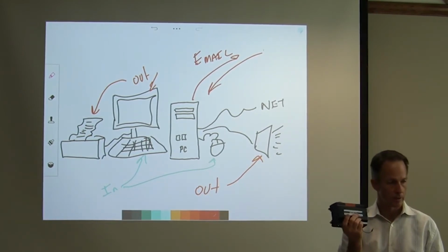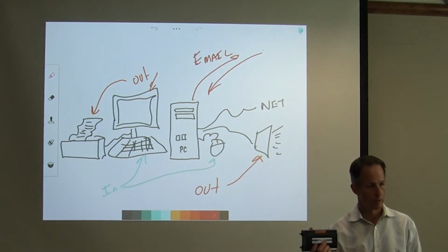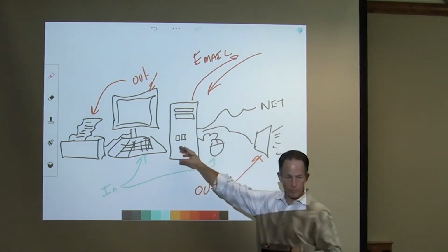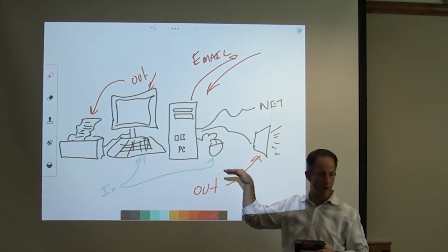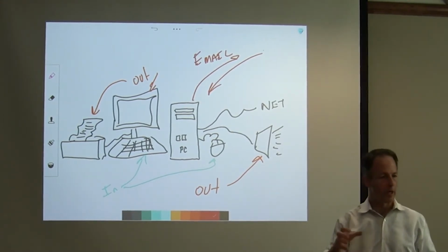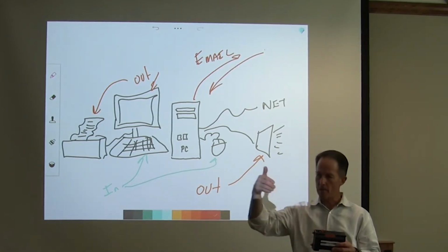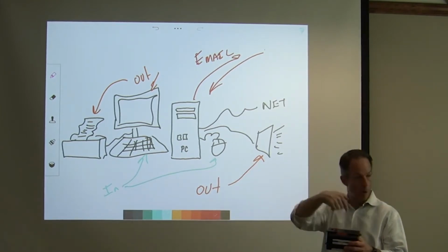You set it up in the supervisor as a network output, and then for each one of the JACEs, you tell the JACE to go look at that network output and tie it to an input. It becomes a point in the supervisor, one of the points that it's monitoring. I could redraw this, but then the next JACE down the line that needs it says, I'm going to look at the supervisor and what points are in the supervisor for me to look at. So it pulls it one more step.